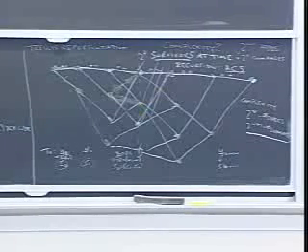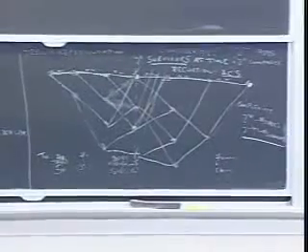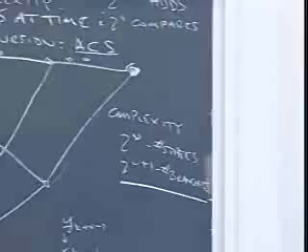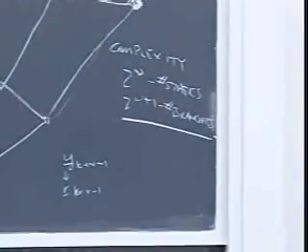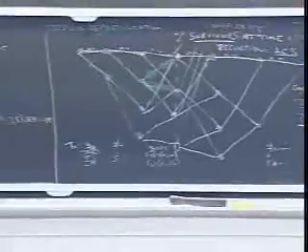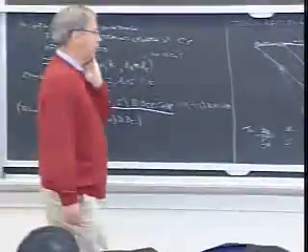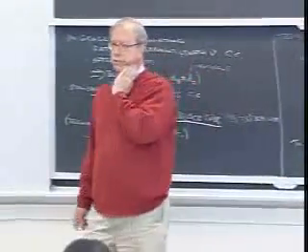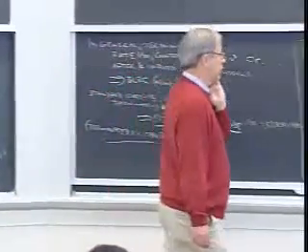It goes up exponentially with the constraint length. This is going to be nice as long as we have short constraint lengths. For longer constraint lengths, constraint length 20 is going to be a pretty horrible algorithm. So we can only use the Viterbi algorithm for relatively short constraint length codes, just relatively small numbers of states.